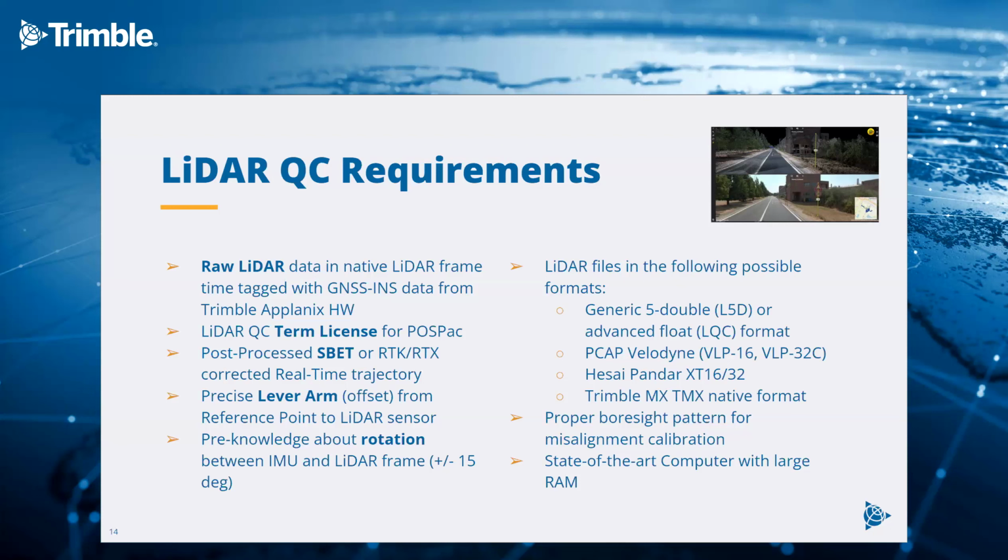In addition, we have some other formats that we support directly already, which are the PCAP Velodyne format for the VLP16 and VLP32, plus the format from the Hesai Pandar XT16 and XT32. And of course, we also support the Trimble MX TMAX native format.